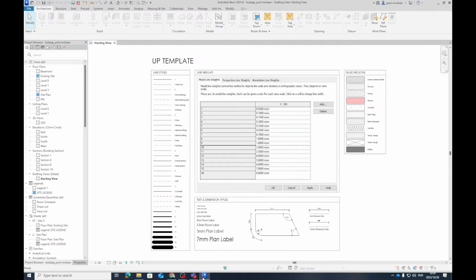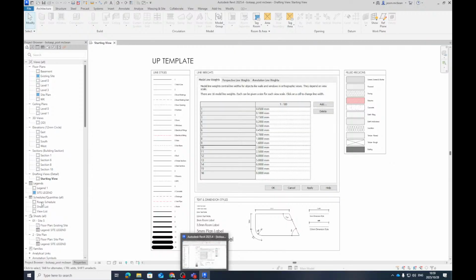Ramps, yeah, so this is the flaw with Revit and ArchiCAD. They use maths to try and produce something. When the maths gets impossible, it can't make it. Because I have a ramp, but because it also goes into the line, I know. That's why it gets so complicated. So I'm going to show you a very quick trick using slabs. Okay.